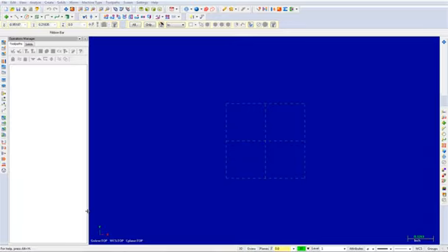We will now create the geometry. The first thing we will do is create a rectangle knowing the width, the height, and the anchor position. Select the Create Rectangle command. Enter a width of -3 and a height of 0.7.